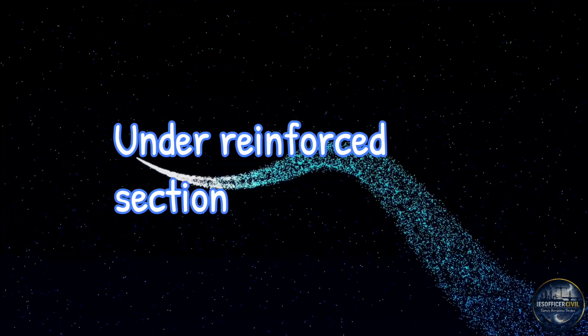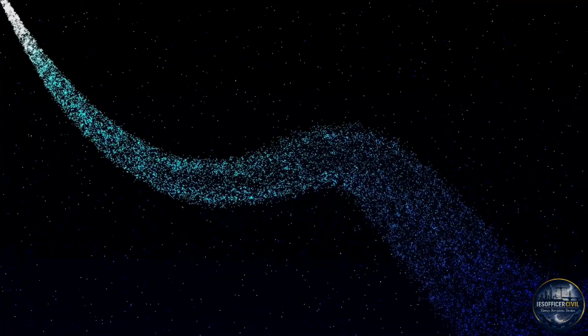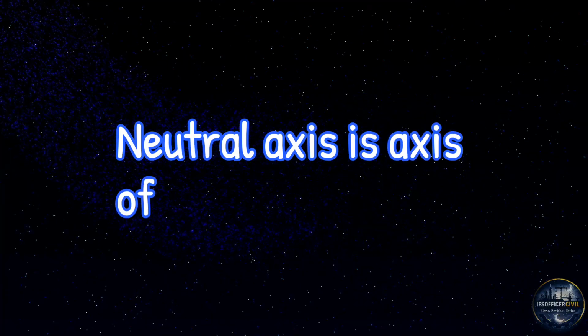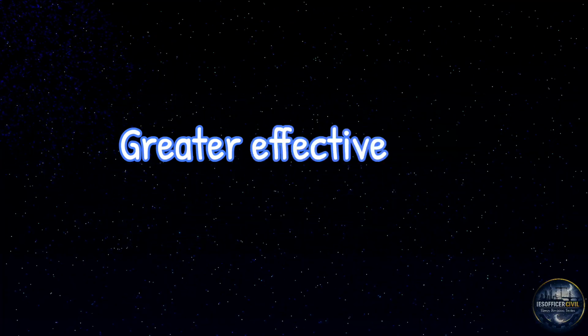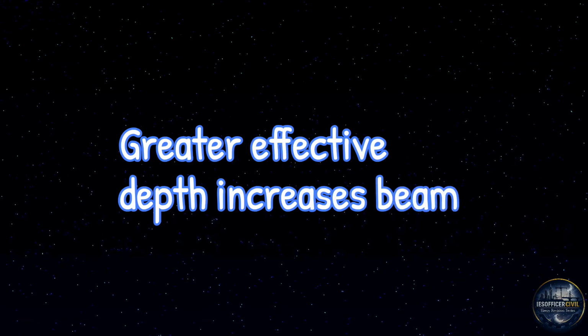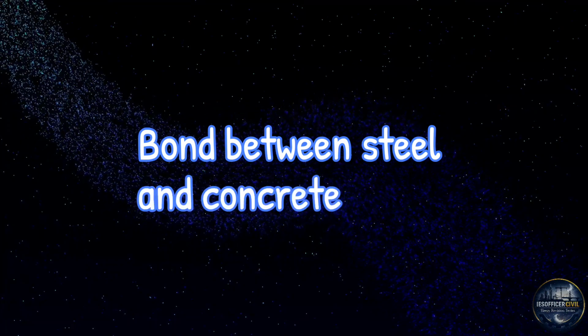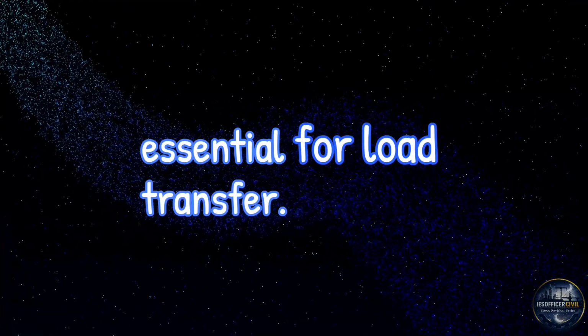Under reinforced section is ductile and preferred. Over reinforced section is brittle and unsafe. Neutral axis is axis of zero stress. Greater effective depth increases beam strength. Deflection is serviceability criteria. Bond between steel and concrete is essential for load transfer.